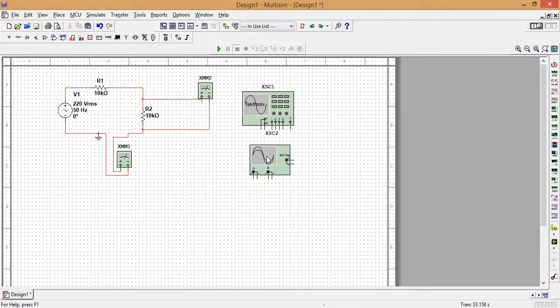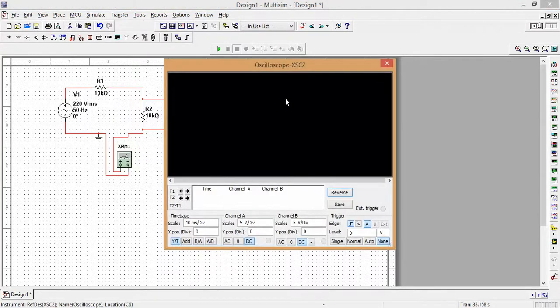When you open the ordinary oscilloscope, it's just some values: channel 1, the volt per division, the Y position, channel 2, same, and the time per division scale. And it will display the sine wave here.